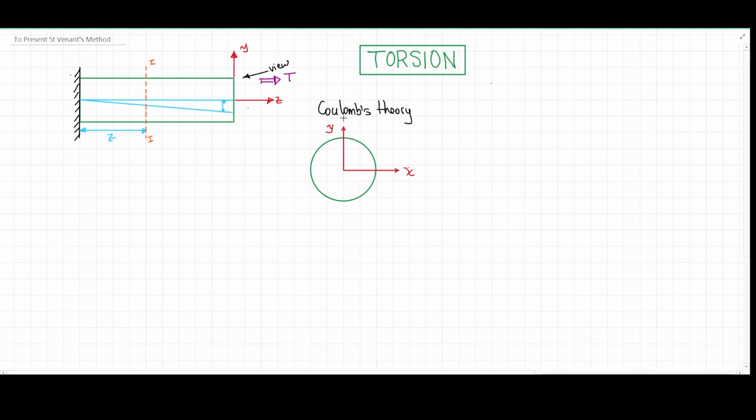So you're going to have some sort of triangular form here. You're going to have a reference line here, and the shear stress is going to increase until a certain point, and that point is going to give me the maximum shear stress at the end of the element here. Let me draw a couple more arrows here, this one, for example, and another one. So this is the shear stress due to the torque applied to these elements, meaning that the torque goes in this direction here.